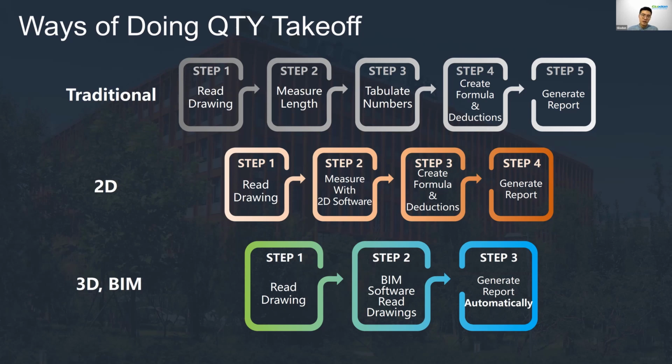It will identify the drawing layers and further generate a BIM model for you. So the BIM model is for QS purpose, not for the design purpose. Once you get the model, the software directly gives you the report, and the quantity, the result. That's how people work with BIM technology. So efficient, straightforward, and easy.